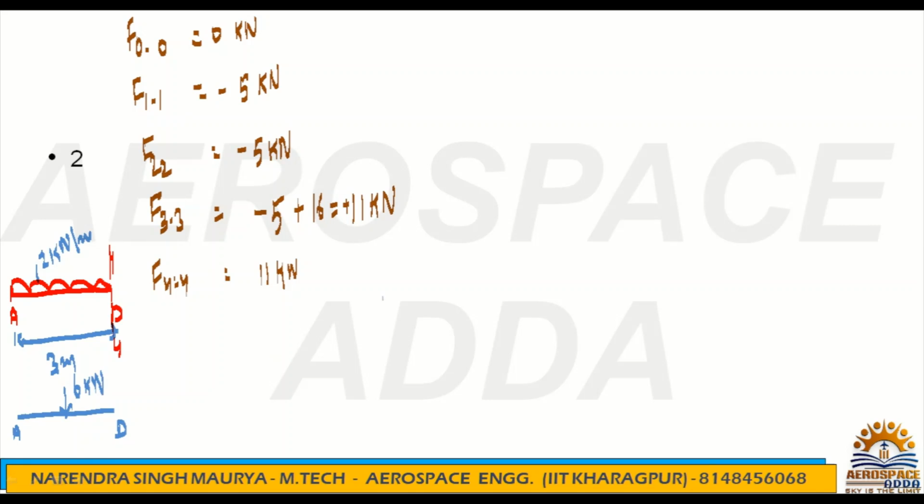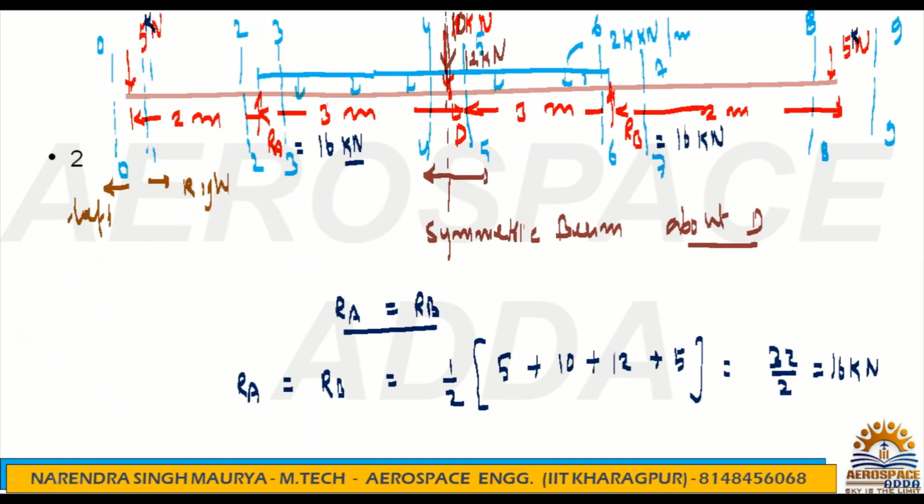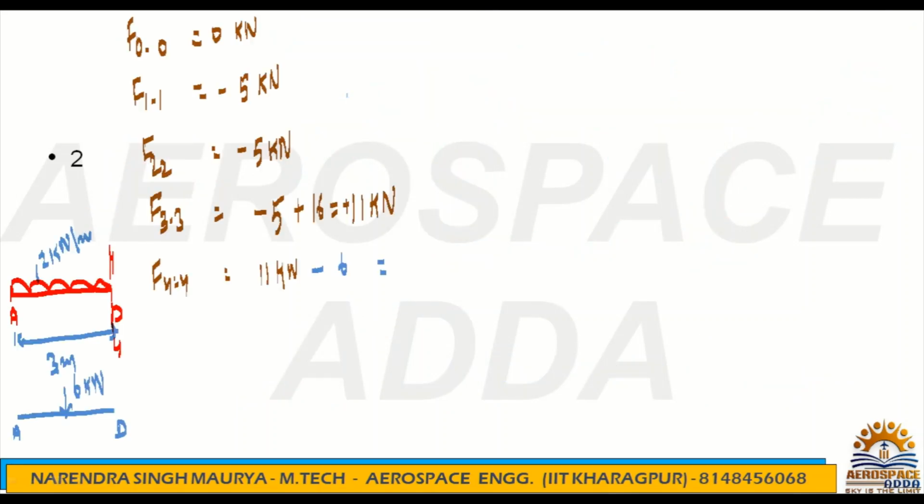This 6 kilonewton will be downside, hence F44 will be 6 minus 6. Because UDL is added between A to D, that's the reason we are getting 2 into 3. 6 is nothing but 2 into 3. So now 11 minus 6, you got 5 kilonewton, plus 5 kilonewton.